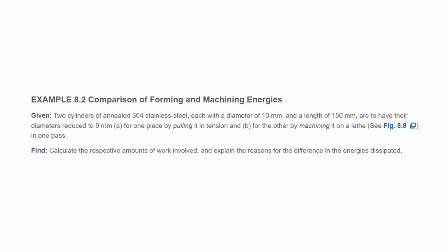U is calculated using this equation: the integral from 0 to epsilon 1 of sigma d epsilon. What do we call this one? The strain energy density. That means this is the specific energy, the energy per unit volume, and you need to do the work.